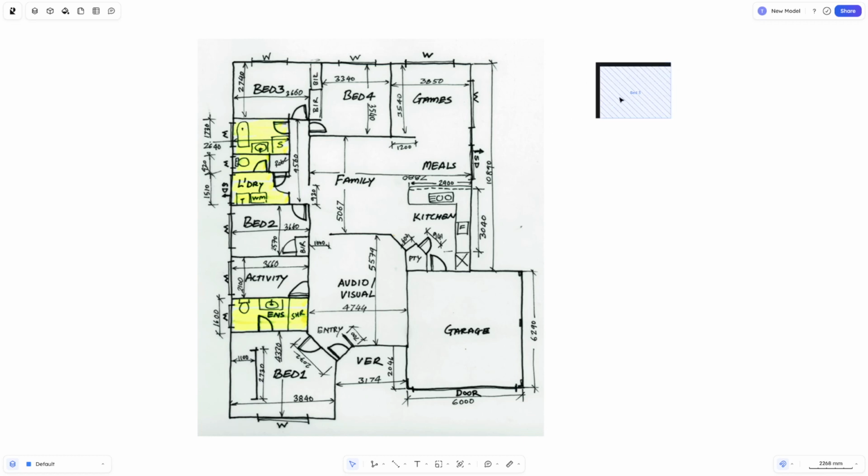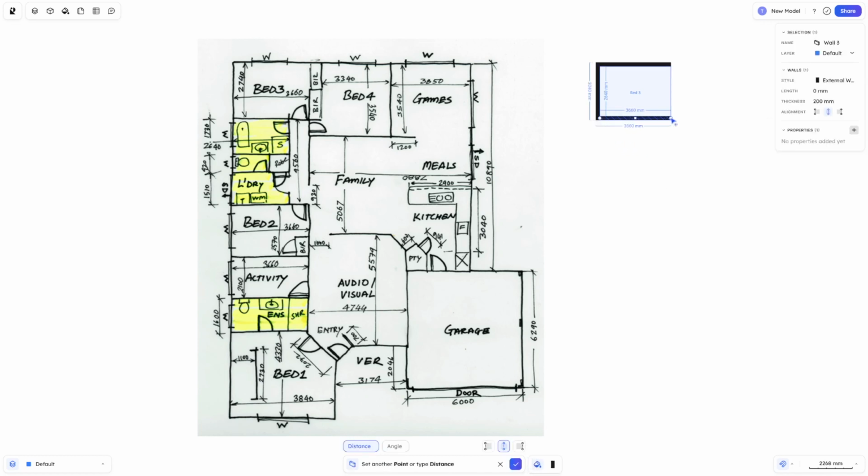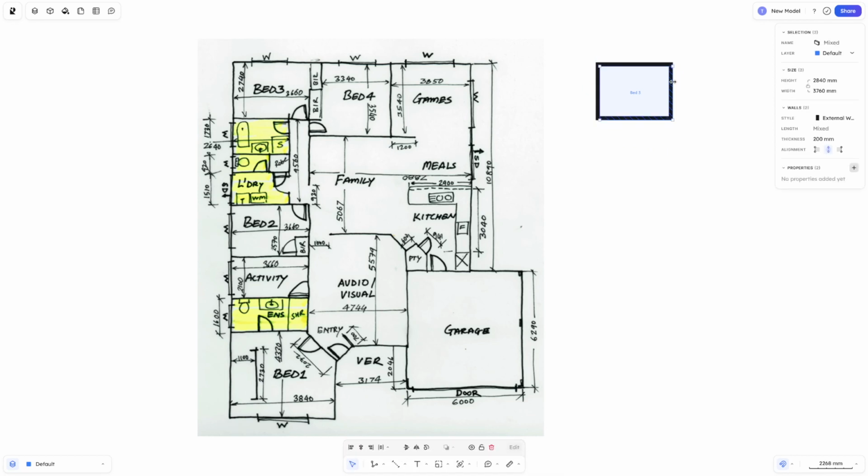So I've drawn it to the beginning of this wardrobe. So what we then need to do is draw internal walls from here. Now the easiest way is if we snap these up here, change it to internal walls, again drop them to the outside. Oop, this one this time. So that's perfectly square in the middle. And that basically gives us this.